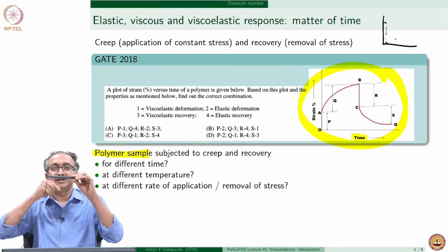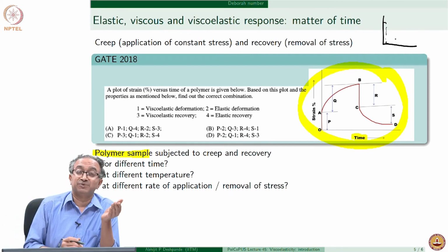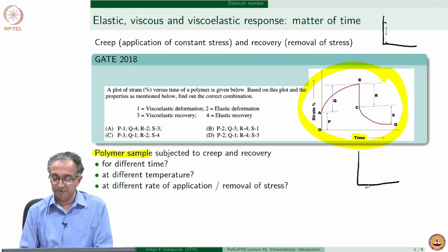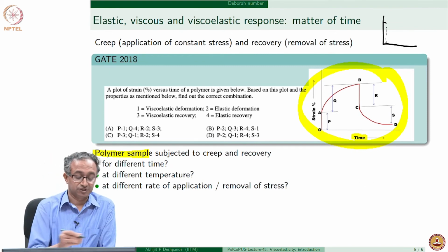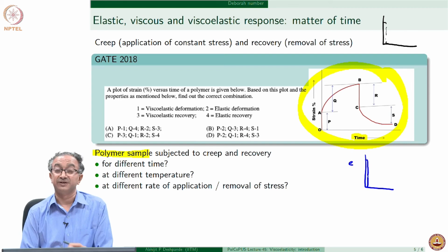So, I take the material, apply stress for an extremely small amount of time and then leave it. Will I observe an elastic response? For example, because the stress is being applied for a very short amount of time, creep is being applied for a very short amount of time, will I see strain? Pretty much like an elastic solid.